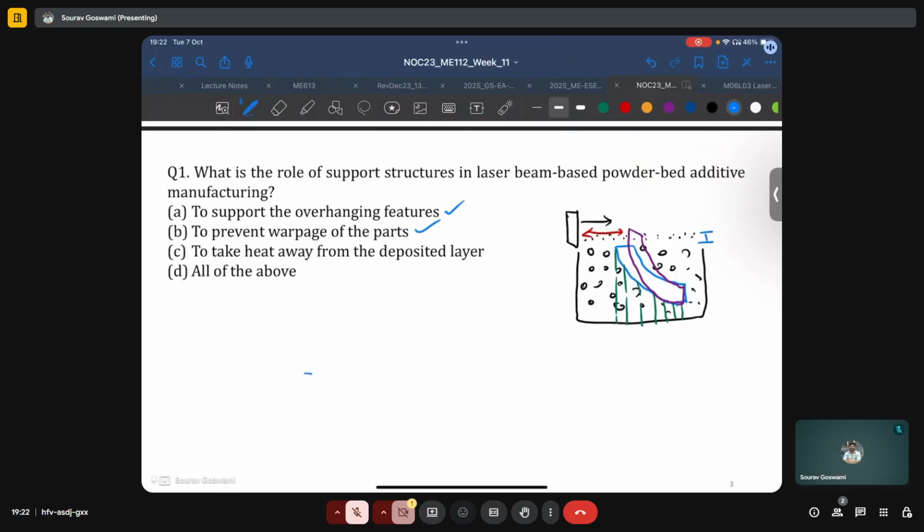It is by convection, so something like some heat transfer coefficient times the actual temperature minus the free stream temperature, and also by radiation, where it is the Stefan-Boltzmann constant times the emissivity times actual temperature to the power 4 minus the ambient or the radiation temperature to the power 4.